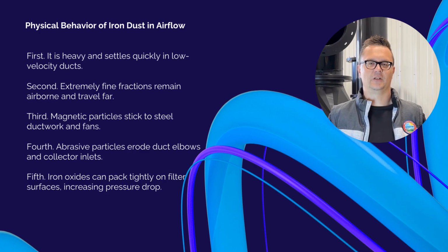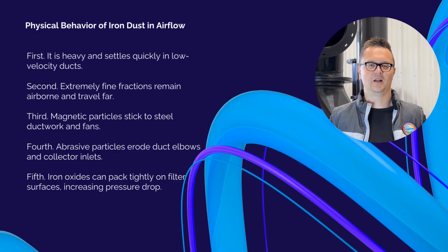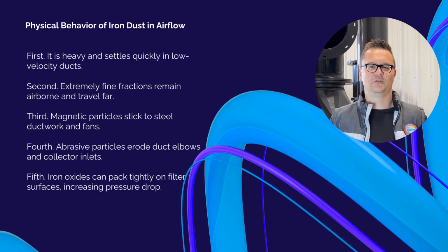Physical behavior of iron dust in airflow. From an engineering standpoint, iron dust behaves in unique ways. First, it is heavy and settles quickly in low-velocity ducts. Second, extremely fine fractions remain airborne and travel far. Third, magnetic particles stick to steel ductwork and fans. Fourth, abrasive particles erode duct elbows and collector inlets. Fifth, iron oxides can pack tightly on filter surfaces, increasing pressure drop. Because iron dust is dense, I design duct velocities from 4,500 to 6,000 feet per minute.